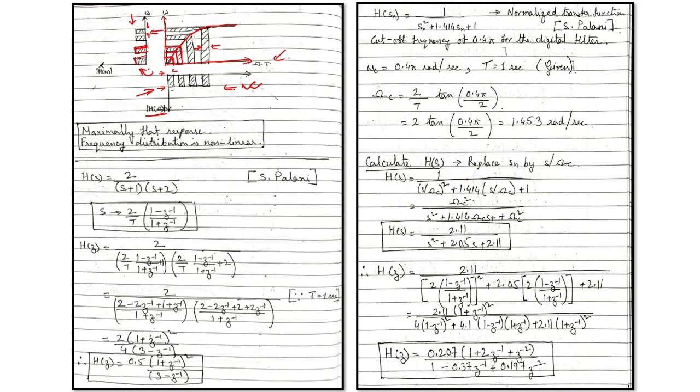But within a specific region, the number of frequencies that are getting compressed is quite high. So designing filters in this compressed zone, by placing the poles and the zeros in the high frequency region, becomes a difficult task. I am not saying it is impossible, but I am saying it becomes difficult.